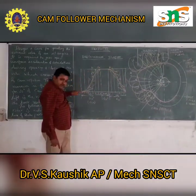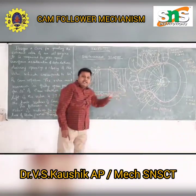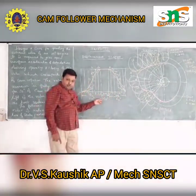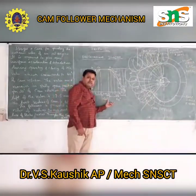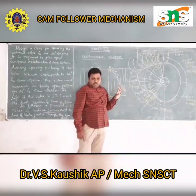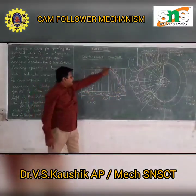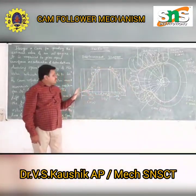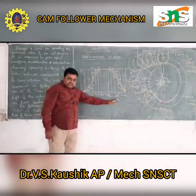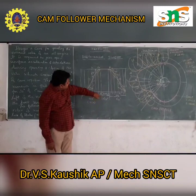See, 37.5 mm height, and from here a total of 14 centimeters distance you should draw. The first 6 centimeters is the outward stroke, the next 2 centimeters is the dwell, and the remaining 6 centimeters is the return stroke. So the rectangle will be formed, and you should separate this into 3 divisions. The first division is 60 degrees.